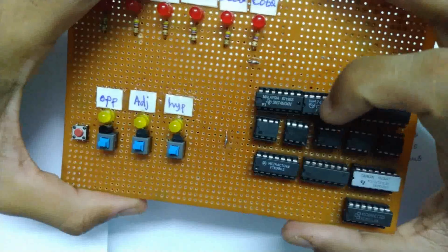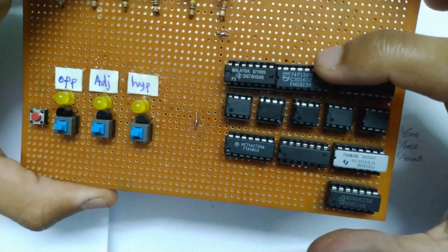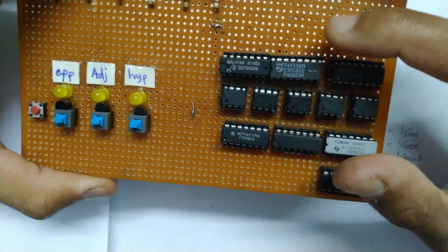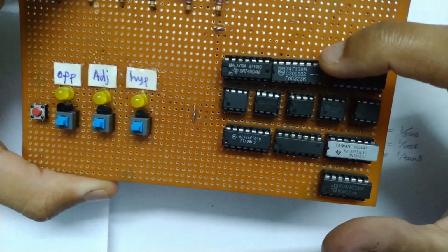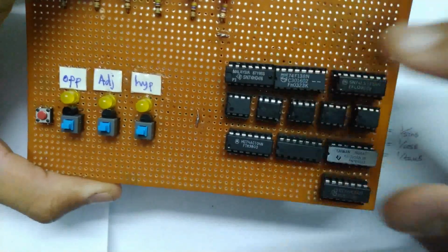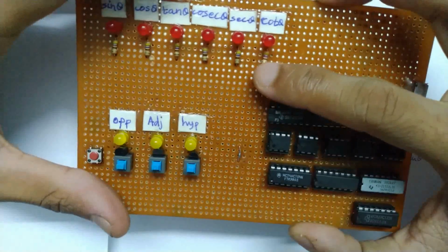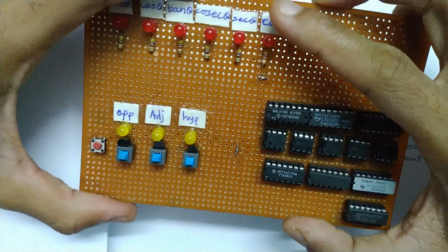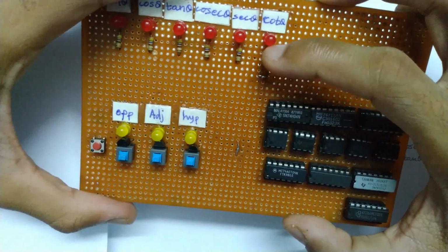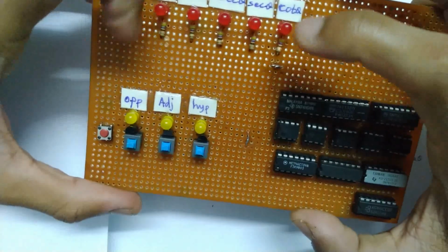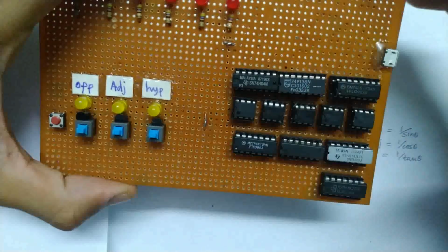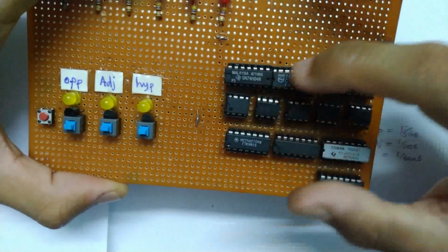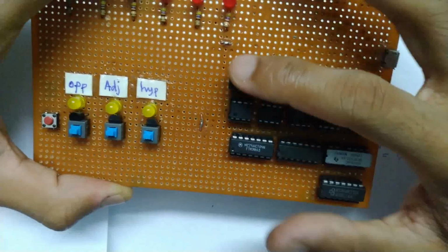The problem was that this IC is an active low output IC, in the sense, if I'm saying an output is active, it means that output has a value of 0, rest all have 1s. So suppose if I'm saying 7 is active, then output pin 7 will output a value of 0, and remaining all the pins will output a value 1. So if I give that 0 value to the anode of the particular LED, then it will be pointless, because I'll be connecting the cathode to ground, and the anode will also be connected to ground through this resistor, so it will be useless, and remaining all the LEDs will turn on because rest all outputs will be high or 1. So that's what made me use this NOT gate 7404, with which I essentially just inverted the outputs coming out of this and gave them to these LEDs.